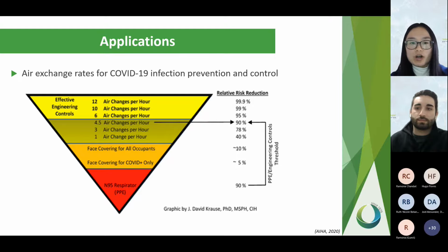there's more pressure on the HVAC system, and not every system is necessarily designed to handle an increase in terms of MERV. So if the system is able to handle it, then of course we want to follow the best practice recommendation by ASHRAE. But if it's unable to, I think it's important to maybe assess upgrading the HVAC system, which may be a large cost, and to see if that's feasible, or come up with other ways to improve indoor air quality.